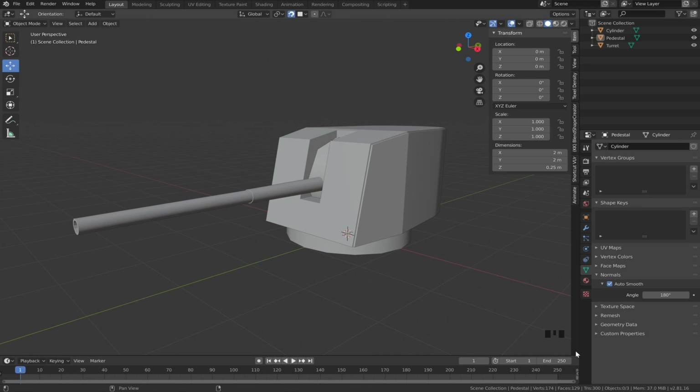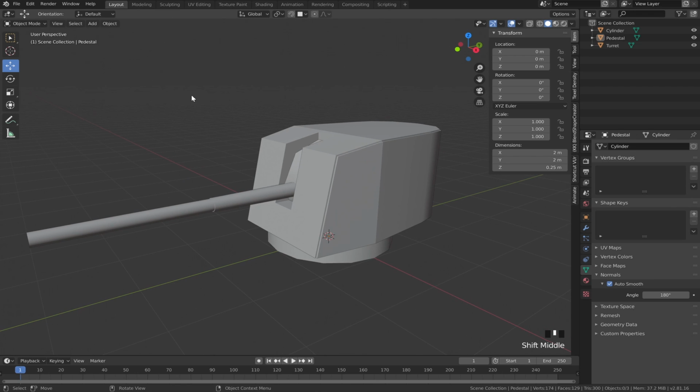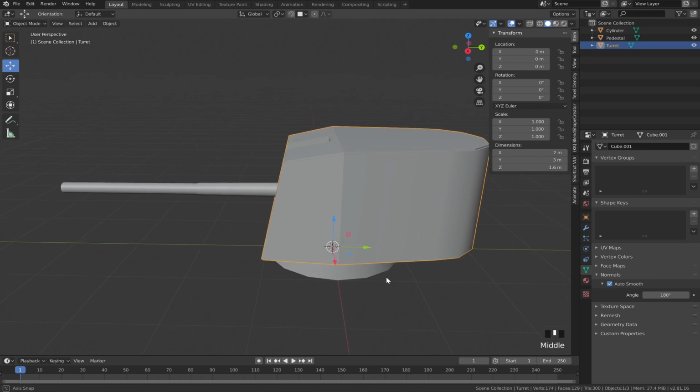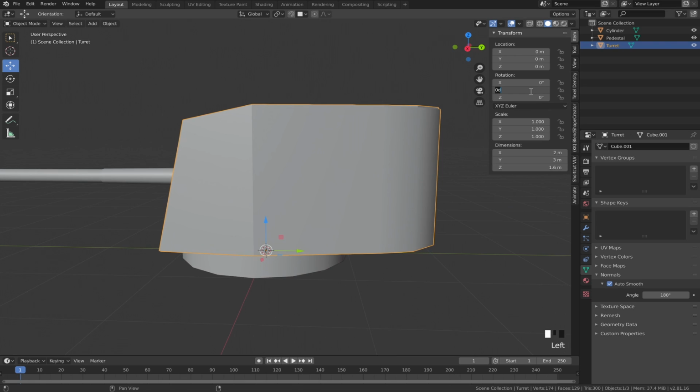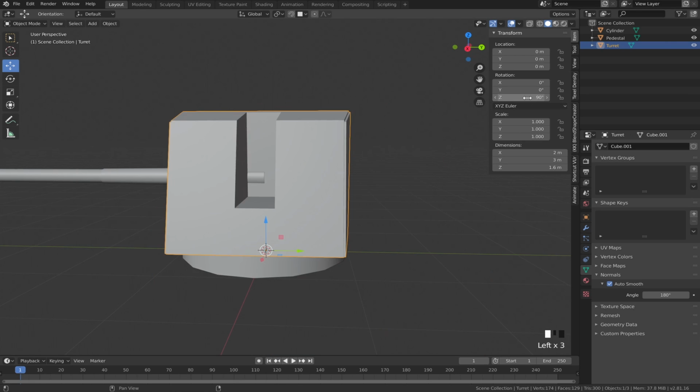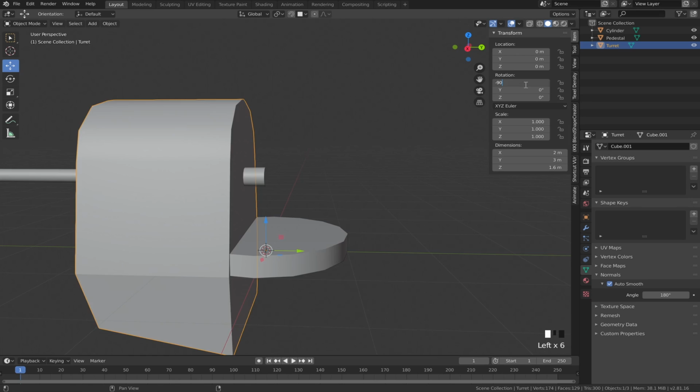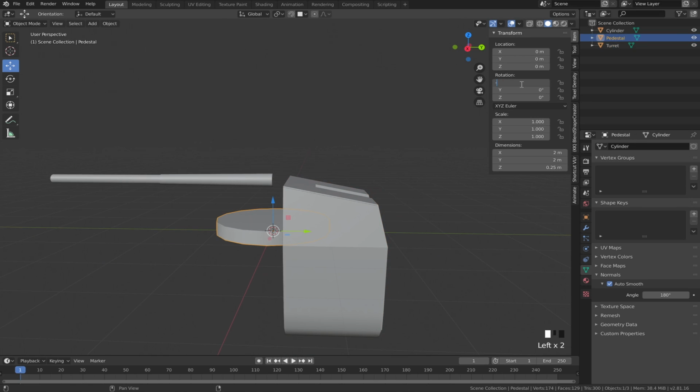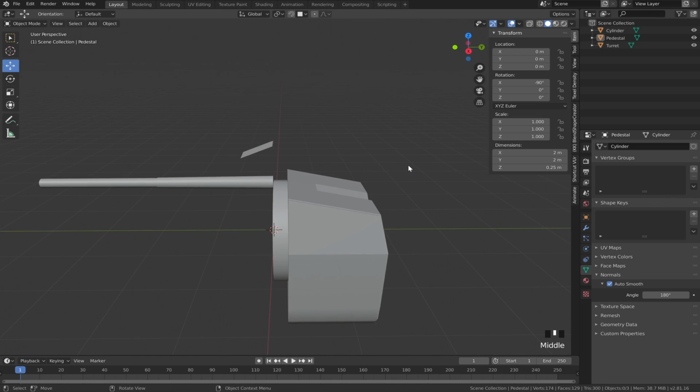Hello, this is Edward from the future. When I was examining the clips I made for this video, there's one thing I forgot to mention. It's important that you remember, when you're finished with your design, that you need to make sure it's in the correct rotation. While this looks perfectly fine, when it's actually imported into Unity, it'll look more like something like this, where it's pointing towards the upper Z axis instead of looking forward.